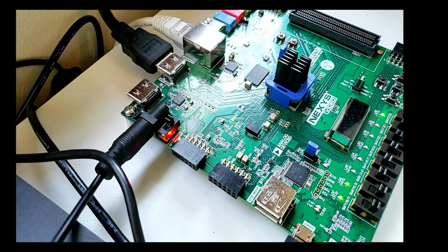In the case of the inverter, each bit of SRAM storage is roughly 6 transistors, and you have to use a whole 6 input LUT for it. It's a several hundred order of magnitude, not necessarily slower, but larger implementation of that inverter. Versus if I knew I only wanted a chip that inverted switches and generated an output, or did any fixed function and never was going to change, you could build it with significantly fewer transistors. It'd be significantly faster, significantly smaller, and better in terms of power consumption.